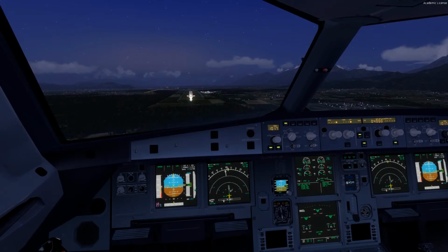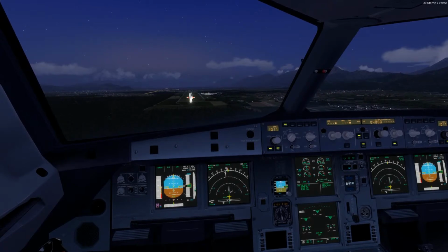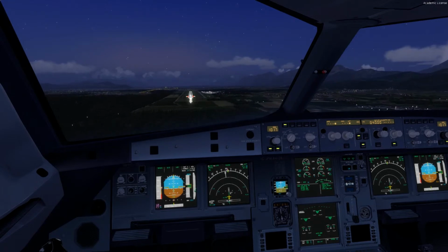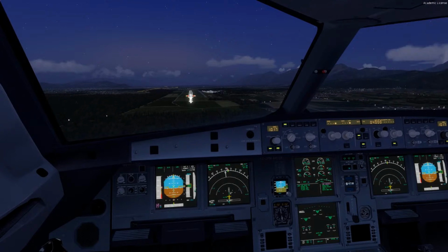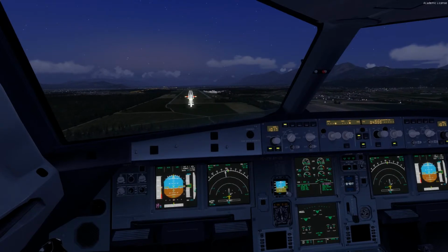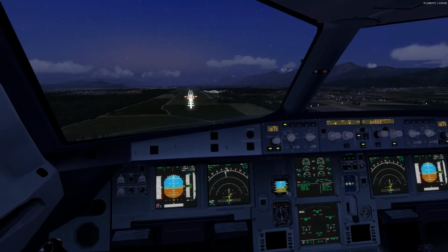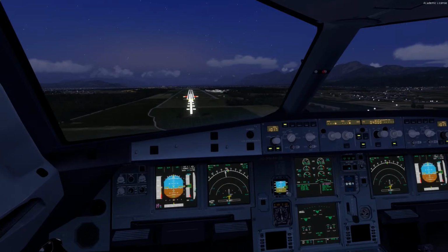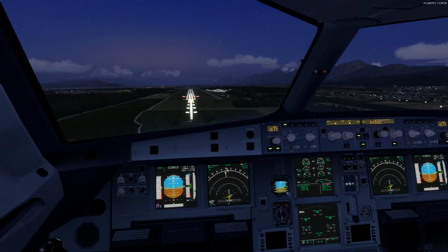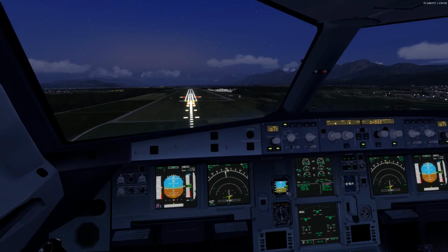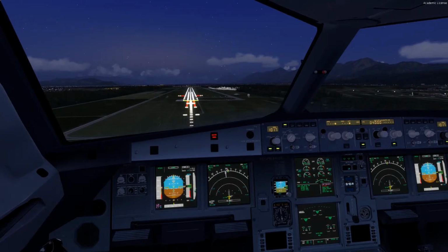And now we're on very short final for runway 30 at Ljubljana, and we'll be landing hopefully now. We still have 2.5 tons of fuel, nearly 3 tons, so that's enough for another missed approach if needed. But we'll proceed now and land and taxi to the stand. 500. Now I will manually continue with the landing and touch down the aircraft, and then continue to Golf intersection for vacating the runway.